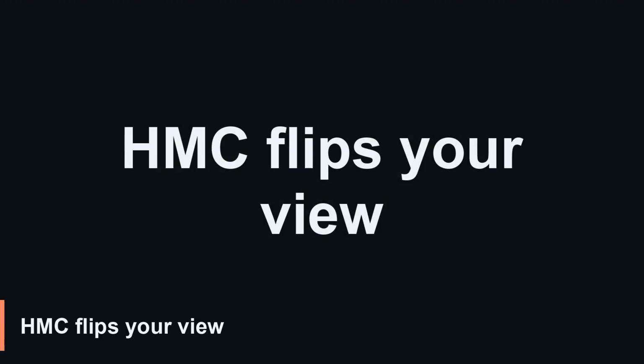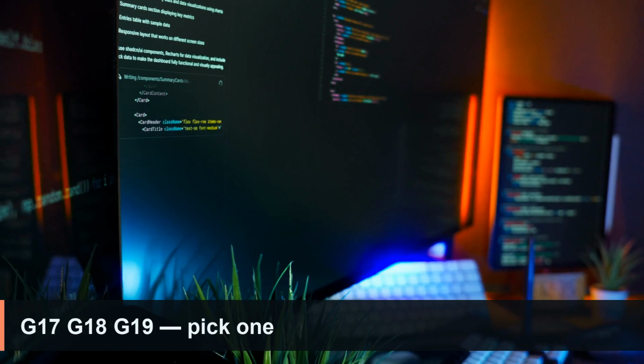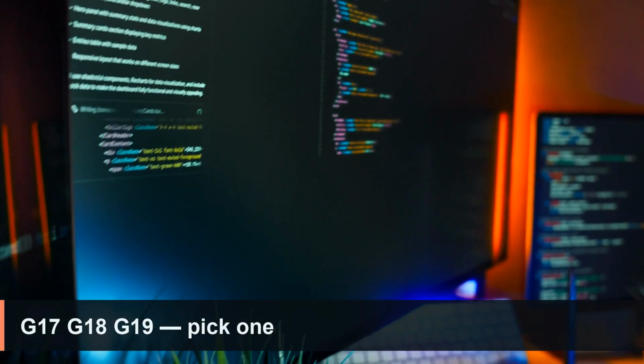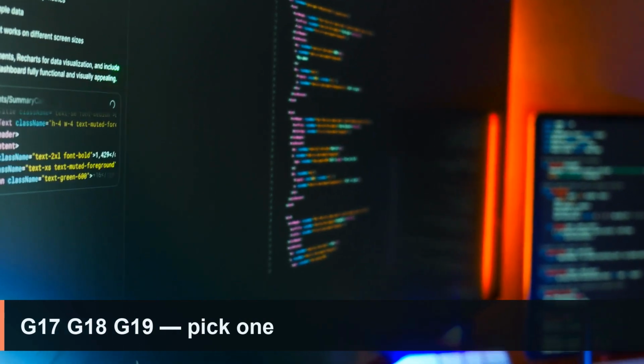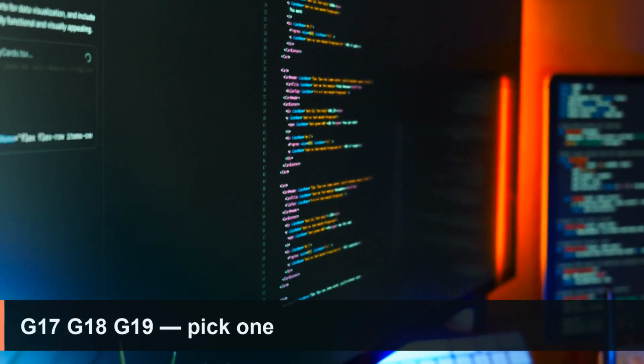Here's where it bites people. Flip the part over on a horizontal mill. Same G02. Same I and J. The arc now sweeps the other way relative to the operator standing in front of the machine. The G code didn't change. The plane did. G17 is XY. G18 is XZ. G19 is YZ.